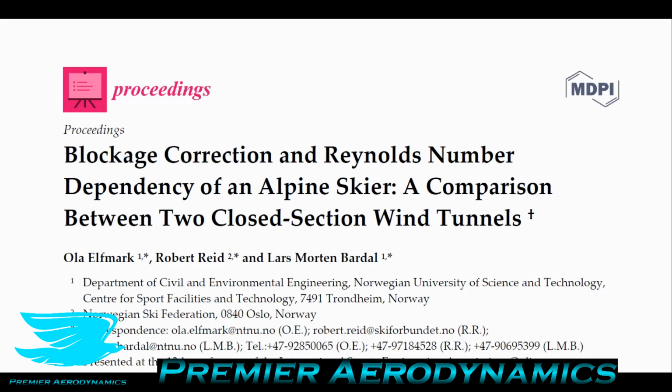The object itself is going to be taking up some of the area of the wind tunnel. So if you have a wind tunnel, let's say, which is 1 meter by 1 meter in cross section, that means you have a 1 meter square cross section, and this object, if it has a cross-sectional area of 0.1 meters squared, it means it's taking up 10% of this area. What this means is that there's less area for the oncoming flow to go through.